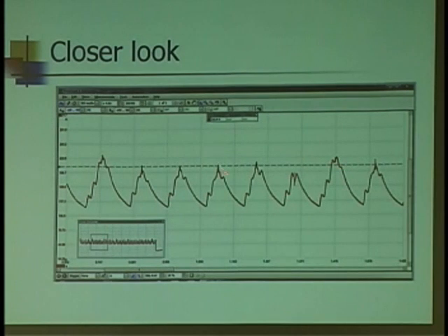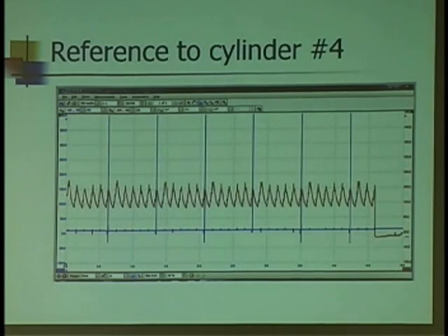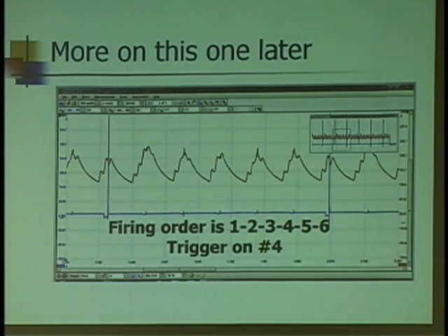Could there be anything else wrong here? Well, we'll see. Now, again, the 3.5 is a transverse V6. It's 246 on the front. I just grabbed number 4 because I need some type of reference point. I want to see where that low peak is. I just got lucky on that one. Happened to be number 4.